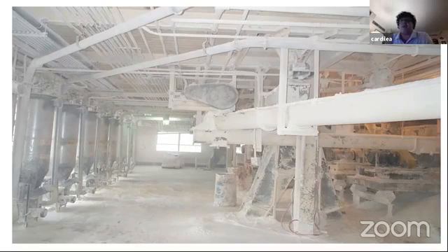The peak shaving is to deal with the demands that are way above what the natural gas company could supply at a given point in time. So it's usually in winter that they do it. You've got a peak, and this place cuts it off: there's a part above it that can't be supplied by the gas company, and this place meets the demand between what the gas company can supply and what's needed, for short periods of time. But at the end of the day, it's how you get a continuous supply of natural gas in the wintertime. And these are literally everywhere in the country. If you have gas, then you're definitely hooked up to one of these facilities.